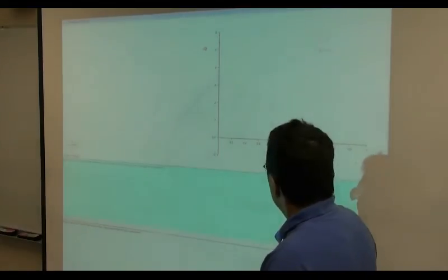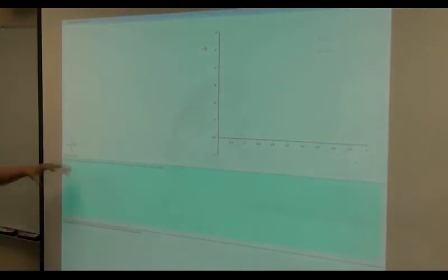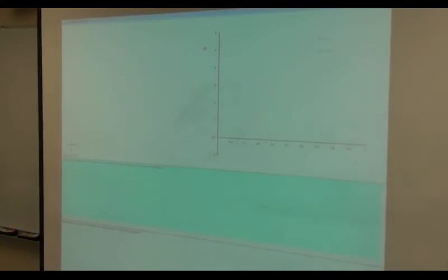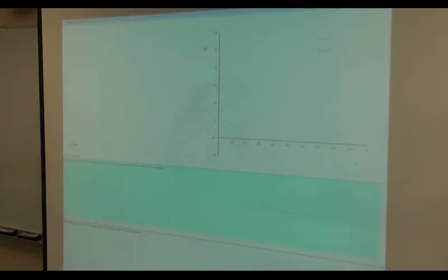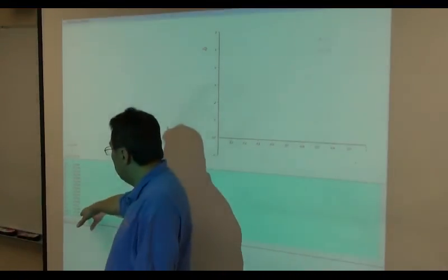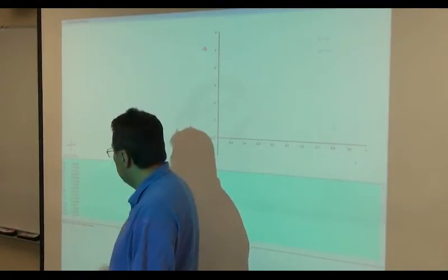Okay. So what you need to do is provide your airfoil coordinate data, which is essentially the panels. Let me just show you a demo. If you just click on the compute button here without any data, this applet automatically loads up the NACA 0012 standard coordinate data here.